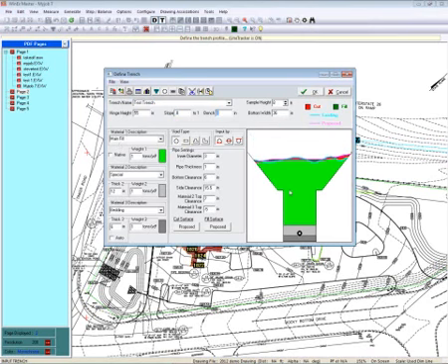We allow you to work with 3 layers here in this trench, and we choose this top layer. We colored green. If you click in here that it's native fill, we will not include it in your import-export numbers, because by clicking native, you're telling us you're going to put it back in the trench, that layer is good enough to be back in the trench. And then you can pick your other 2 layers, and you can add to that. It's a customizable library.